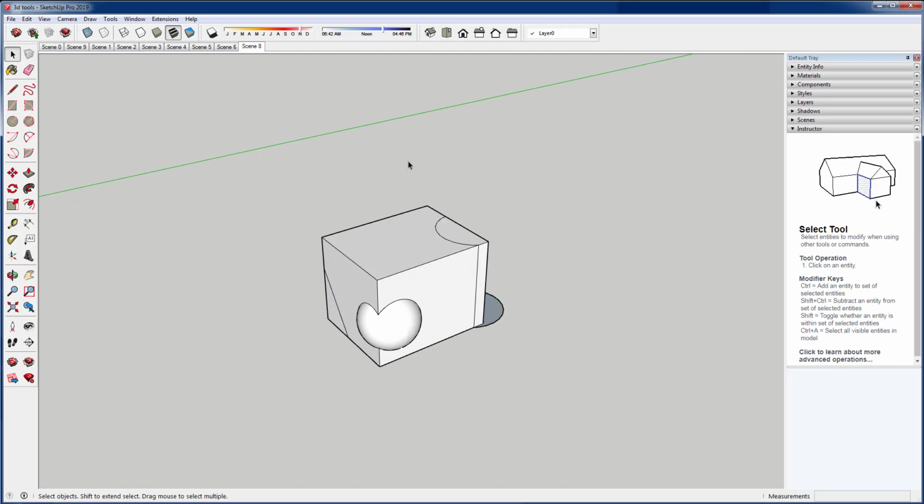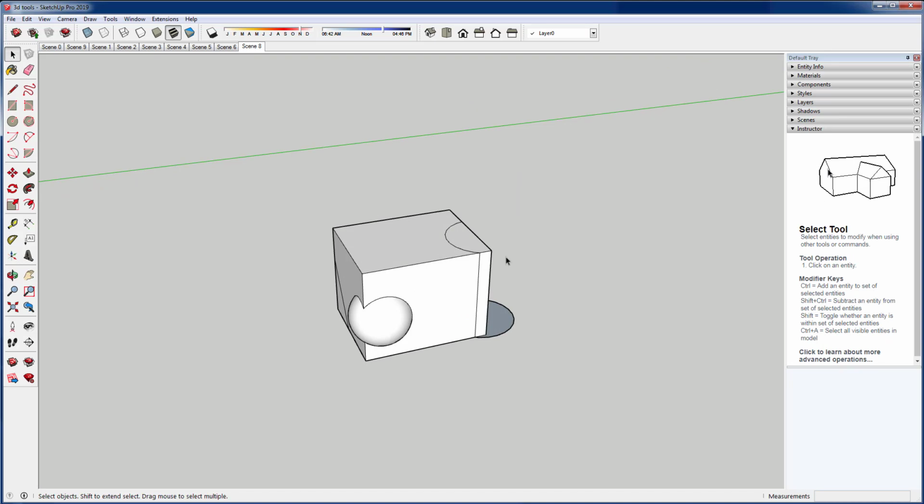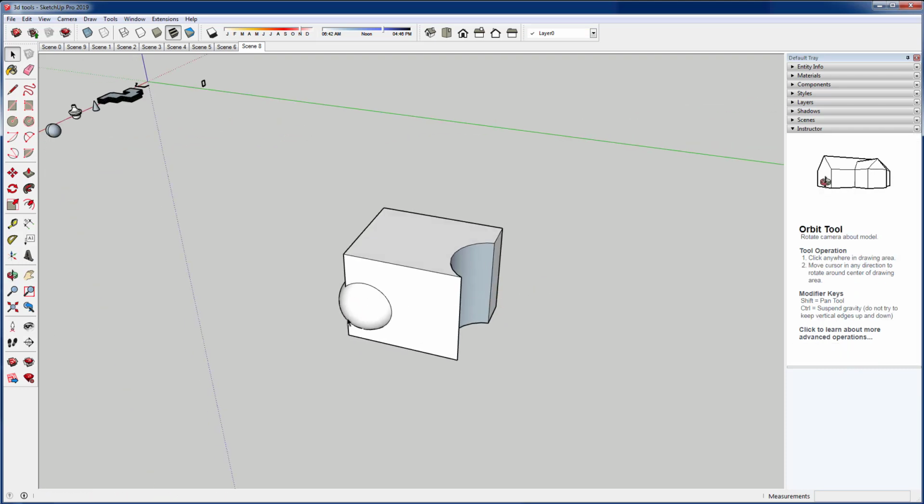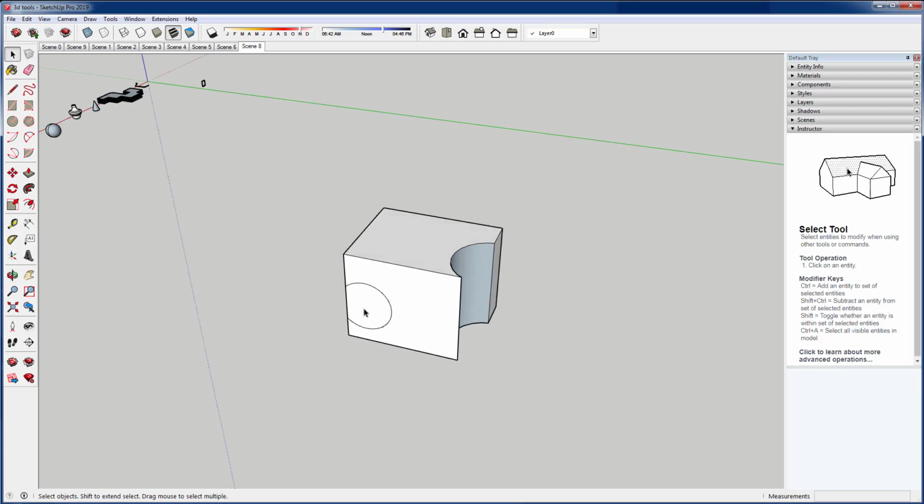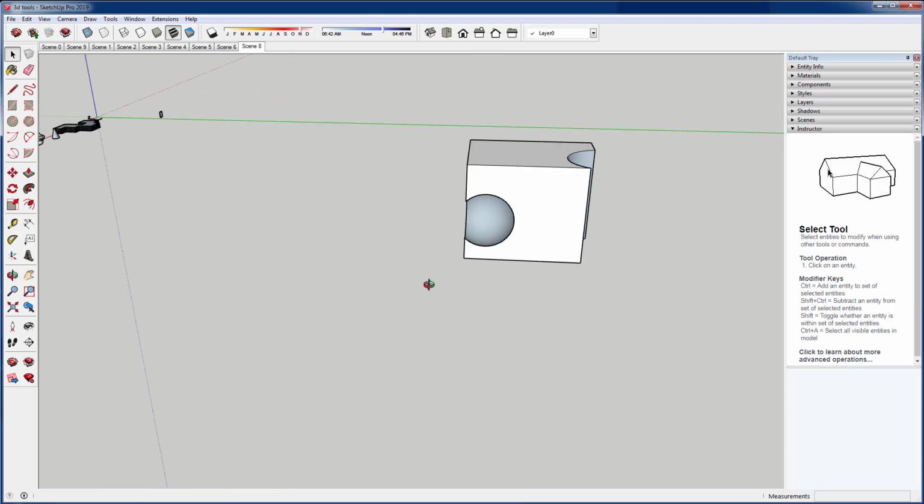Okay, so the Intersect with Model, you might not be aware of some hidden geometry that might be there when you make the object, and that would just cause some major headaches. Okay, so that's the difference between the Intersect Model and Intersect with Faces selection.